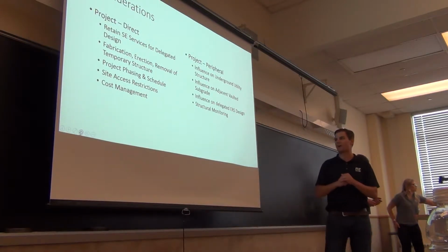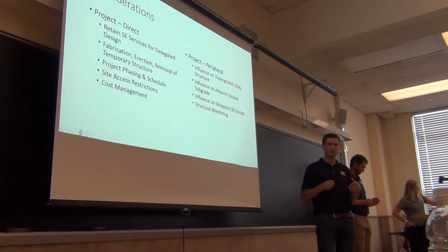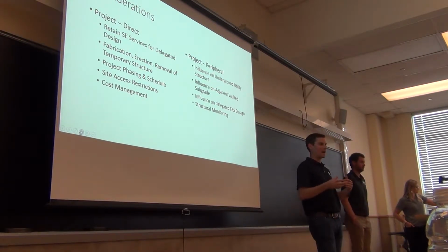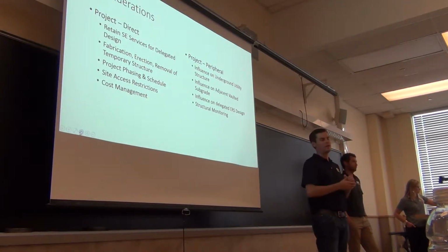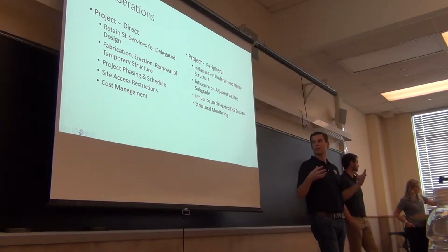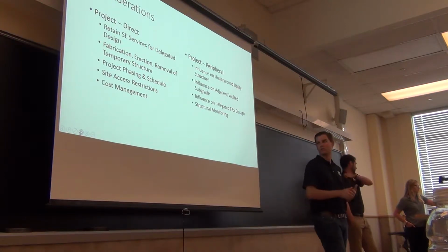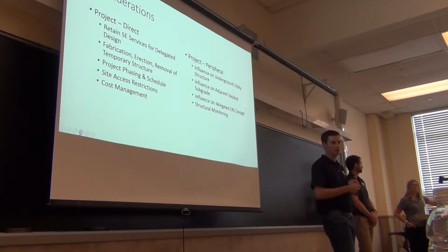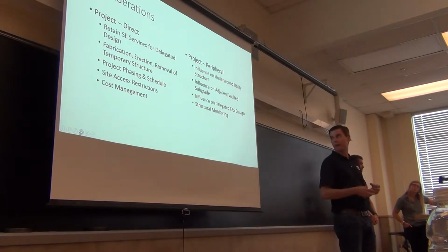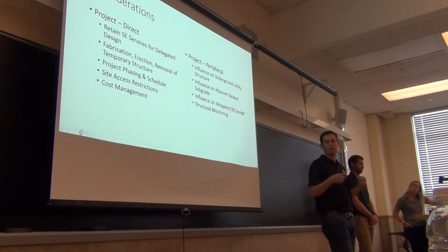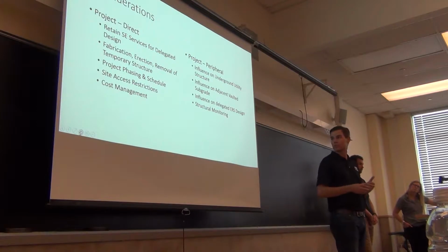I talked a little bit about project phasing and schedule. Keep in mind that you can only do 2 of these locations at a time. It's a really time-intensive process to kind of leapfrog that, and at each location, then you have to erect the shoring structure, take down the columns, demo foundations. We also had drilled micropiles that were even below the foundations that are shown on your cut sheet. Then it was pouring the pile caps, installing new columns. Then we could take down the temporary structure and move it to the next location.